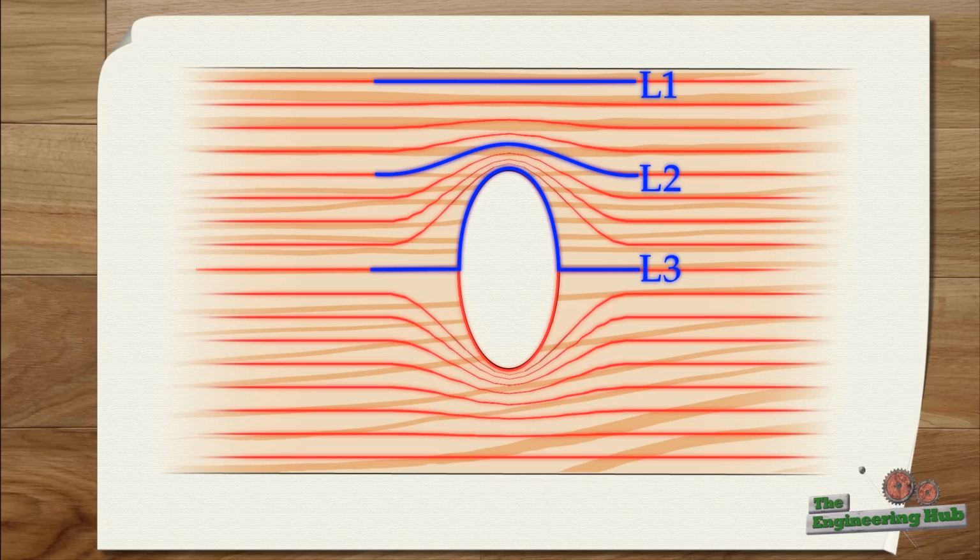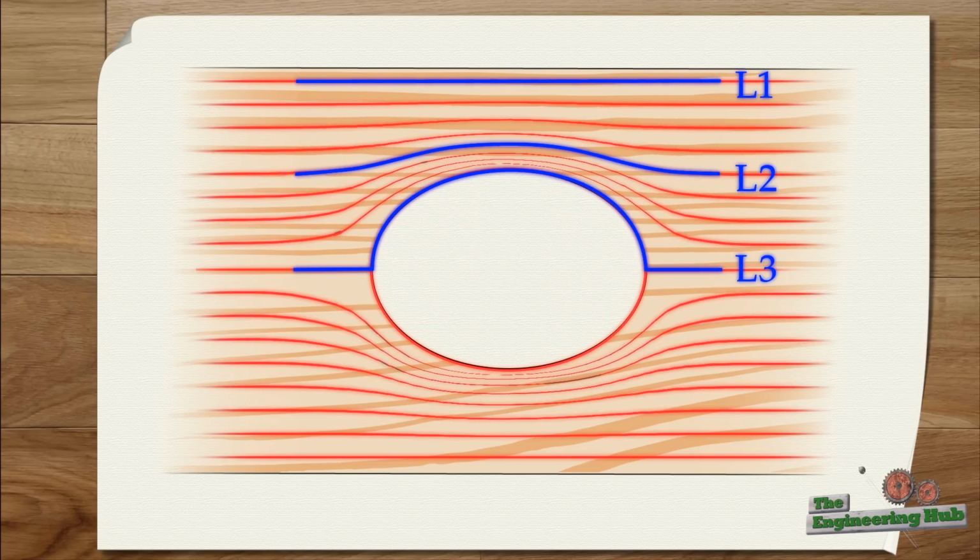Since lower velocity translates to lower stress, one answer is filling in the hole, but that's kind of boring, so alternatively, we can shape the hole in a way that provides a smooth path for the streamlines. This is very counterintuitive when thinking in terms of mechanical strength, since it indicates that removing material is supposed to make the element stronger. However, thinking in terms of fluid flow, we can identify that the fluid should indeed flow more smoothly around the hole. So let's find out if that is the case.